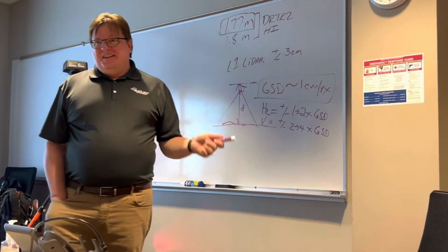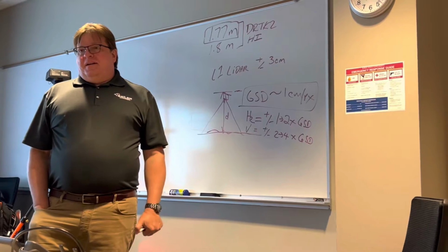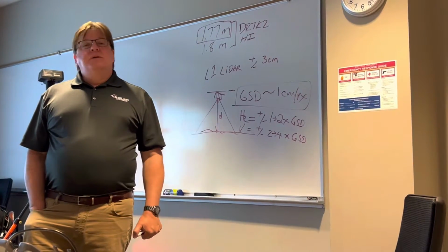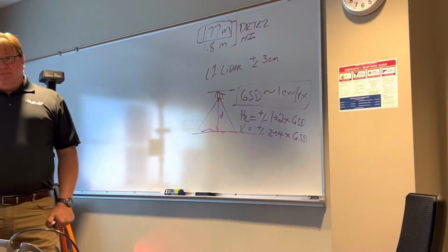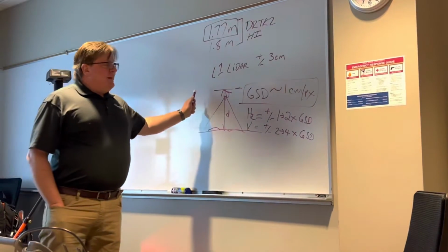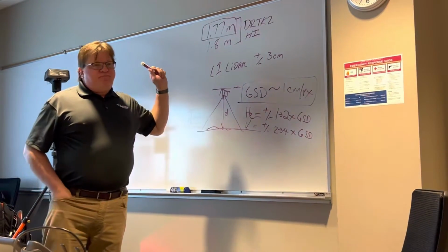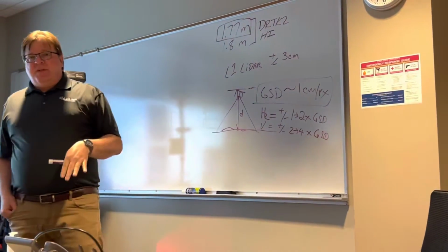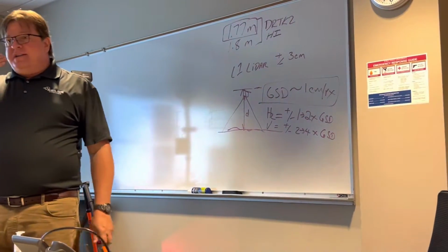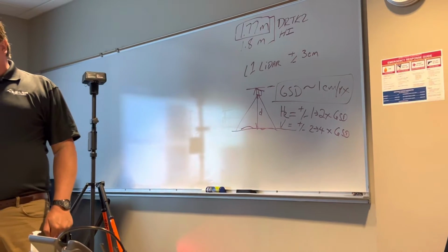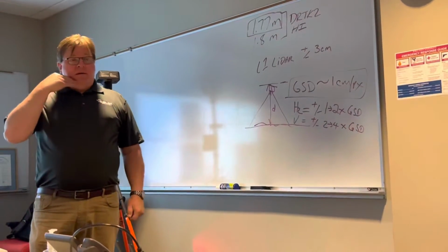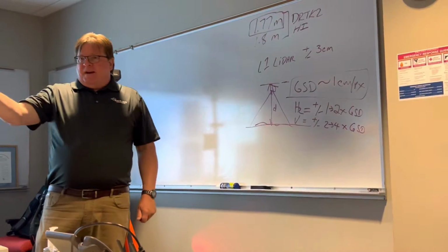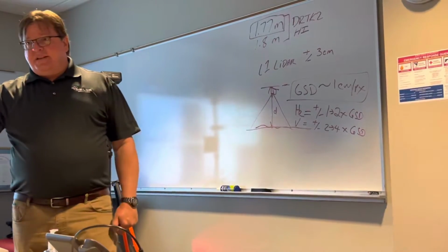And how is this horizontal accuracy with LiDAR? How does that compare to photogrammetry? Different animal. Okay, photogrammetry is a mathematical, formula-based model based upon passive light conditions. LiDAR is an active laser source. Okay, so it's using speed of light divided by time to calculate distance.